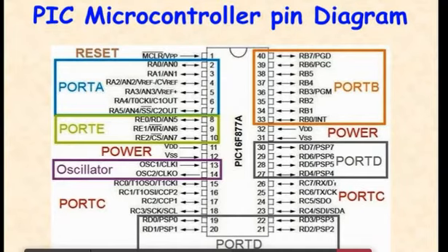Generally in all microcontrollers like 8051, PIC, ARM, AVR, we are using a crystal oscillator. So we'll keep that habit for PIC also. So you have to connect the oscillator here. Oscillator is very important. Without oscillation, it will not execute any instruction.